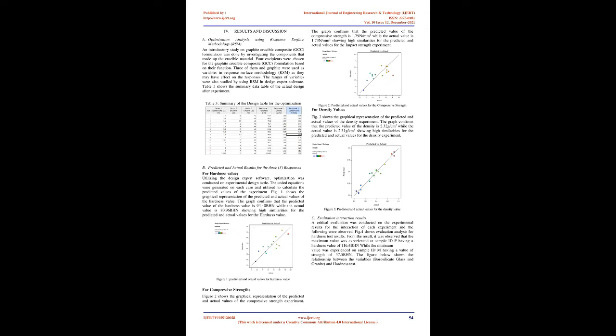Furthermore, samples were subjected to chemical analysis using Shimadzu X-ray fluorescence spectrometer EDX720 and thermal analysis using TA Instruments high-res TGA 2950 thermogravimetric analyzer, respectively, in order to check the stability of the test samples. Thereafter, grinding of the stable test samples to 500 microns was carried out using a 5 kg laboratory ball mill, Umuahia et al., 2017. The samples were sieved through 500 micron sieves to obtain materials containing a distribution of particles with maximum particle size of 500 microns.